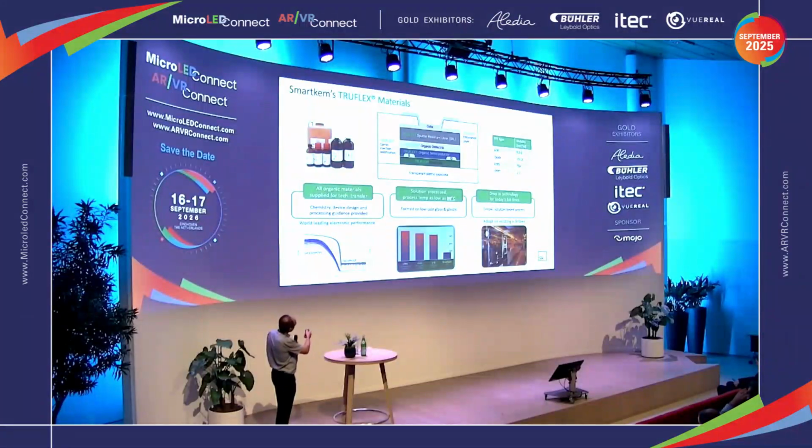The semiconductors themselves, if you compare them with existing inorganic materials, have a mobility of around 2 to 3 in short channel devices, which is higher than amorphous silicon, but lower than oxide TFTs and much lower than LTPS TFTs. This shows some of the transfer characteristics of typical devices. We're trying to optimize the uniformity, very low off currents for power saving, as well as getting a reasonable mobility for driving current.